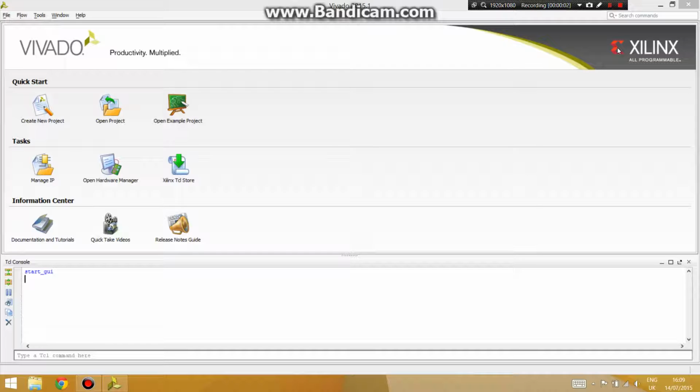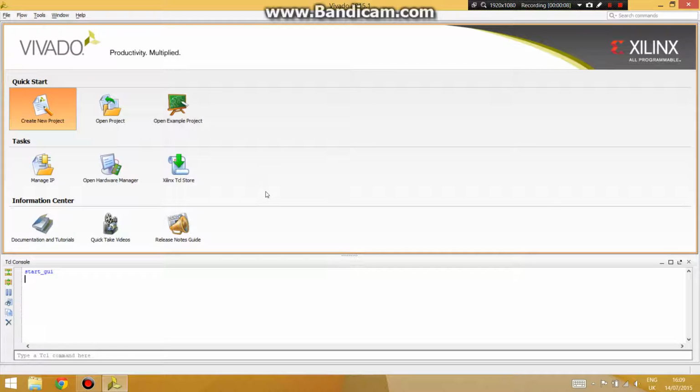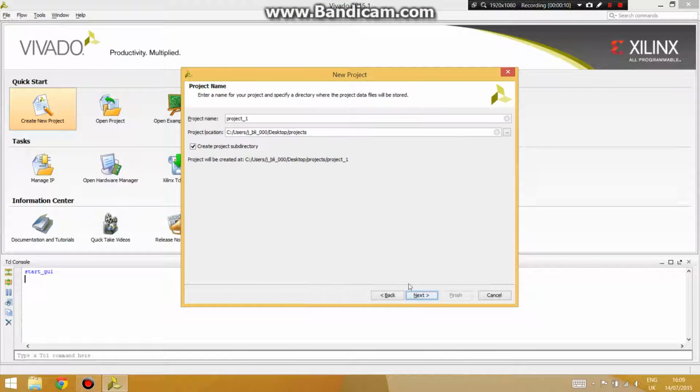We're gonna do right now what we have done for ZedBoard on the very first video. We're gonna do for ZedBoard now. So let's create a new project here. I'm gonna call this project name ZDemo1. You can call it whatever you want, just make sure it has no space in the project name or in the project location.